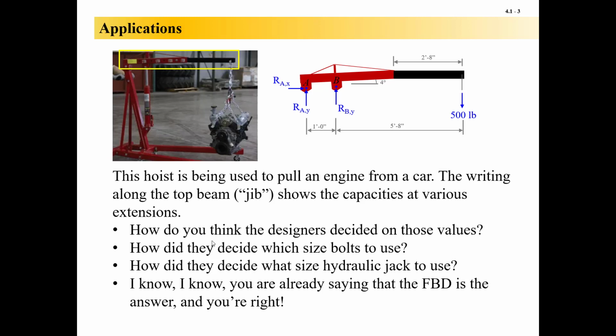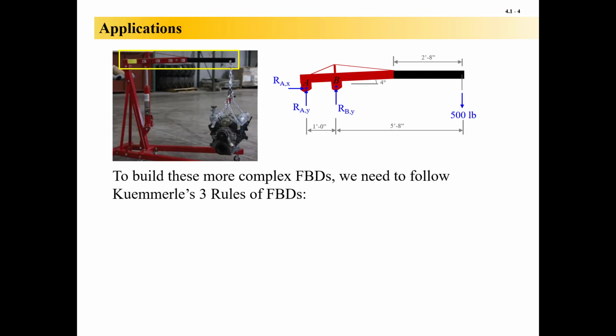And the important thing is free bodies are absolutely, without a doubt, the way to solve these problems. Now, you've done free bodies of particles, and now we're talking about rigid bodies. The difference is that there are dimensions on it. There's more than one point. Before, it was always the ring all these cables are connected to, or some point that multiple cables or ropes connect to, and those all have axial tension and compression forces emanating out from them. So all of the forces were concurrent.